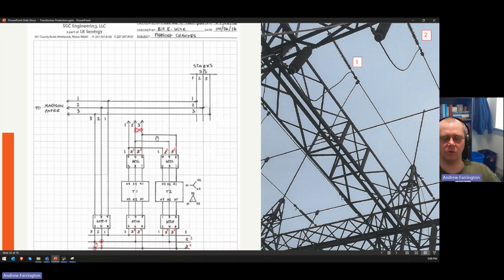And I said, well, that's great. We can just close that switch and then open these breakers and take your transformers out of service and do our changes, and then we can close everything back in, close the switch, and switch back over to, or open the switch back up and switch back over to the municipality's power.